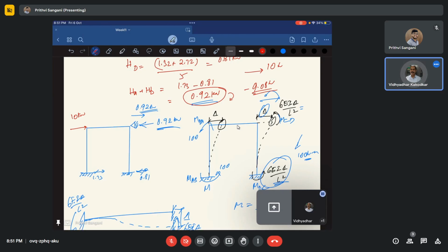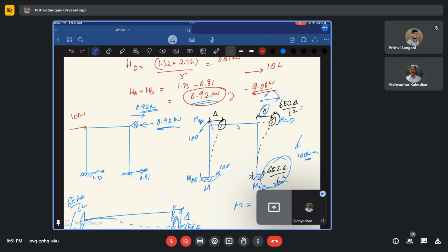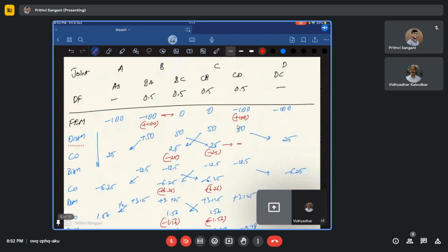If it is acting at the mid of the column also, we have to follow the same procedure. Because at the mid we definitely have fixed end moments, but we are actually not considering the shear forces, the support reactions. So definitely you need to do this net forces. Similarly, you will have the same thing, but in that extra you will have added fixed end moments also coming, if there is a force acting at the mid span in the columns. Okay. Anything else?